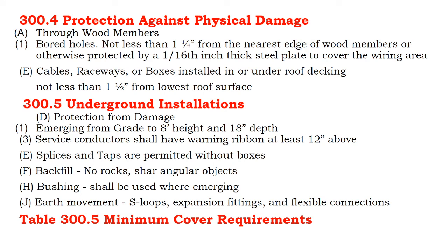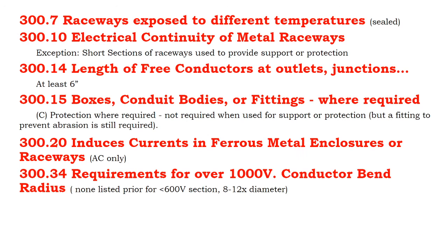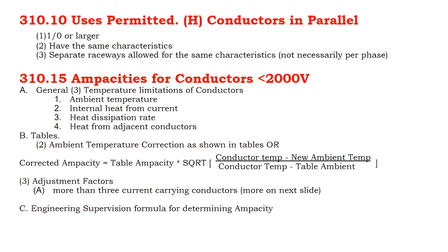The section 300 of code gets into wiring. And so we're talking about how to wire through a home, how to wire underground, and how to wire within a raceway. So when we're wiring within a raceway, whether it's a metal raceway or a plastic raceway, how to route the grounding through that comes down to what bits and pieces of conduit design are you using? Are you using the conduit as a ground path or not?